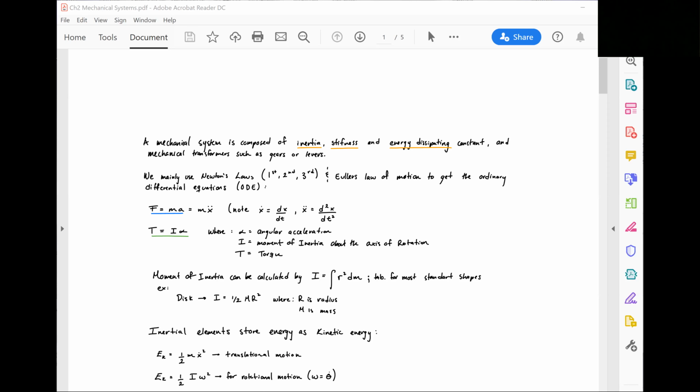Right? And there is an example for the bridges. If it wasn't for damping, in fact, you can watch on YouTube, there are bridges that just due to the wind, they collapse. Why? Because it swings, and the natural frequency of the bridge is the same as the frequency of the wind. So the bridge absorbs energy more and more, then it would collapse. For tall buildings, it would be the same thing. Sometimes when you want to build tall buildings, you have to have some damping mechanism.